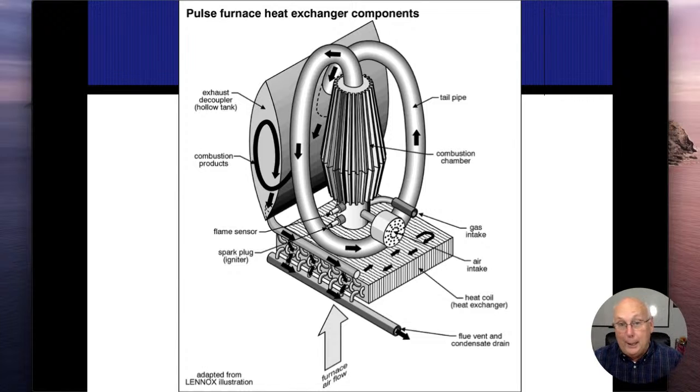They were very problematic. This is where you start seeing decouplers on ductwork, because these would vibrate when they would run, just like you would feel the vibrations of a lawnmower running. These would rattle the entire ductwork. So they would have to put their plenum up, and then put about an inch or 6 inches of rubber ductwork or some sort on there.